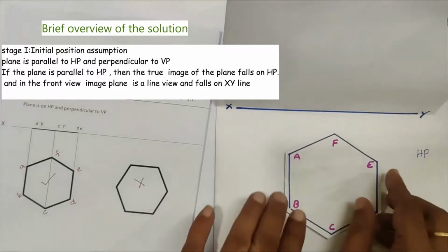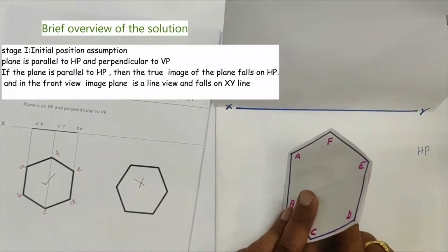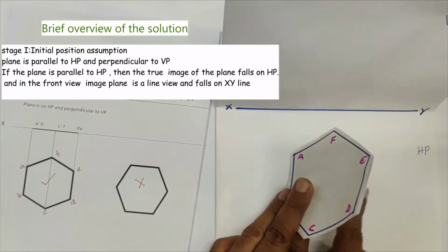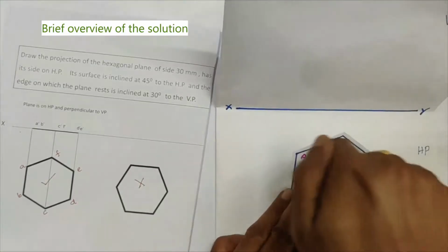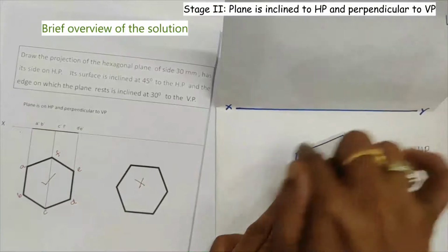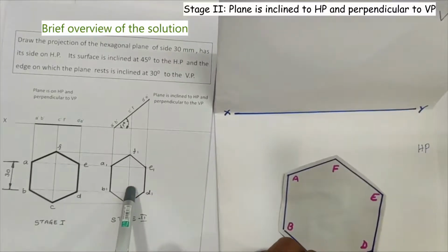Then in the second stage, we are tilting the plane in such a way that this plane is resting on its side AB on HP and its surface is making an angle of 45 degrees to the HP. That means in the front view, it is a line view which is making an angle of 45 degrees to the XY line, whereas in the top view it is a reduced image of the plane because this plane is inclined to the HP. That's why on HP you will get a reduced image of the plane. This is the first stage solution and this one is the second stage solution.